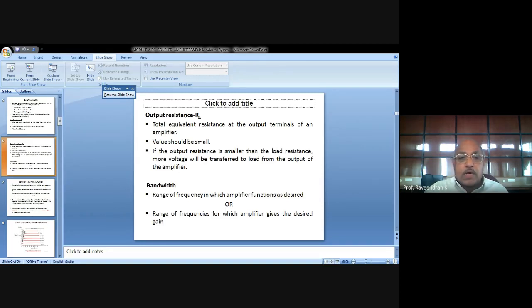You are connecting your signal generator output, that is the input to this amplifier stage, between the base and the emitter through this capacitor, so that only the AC signal will pass through the capacitor and block the DC supply or DC current. So that it maintains the DC operating condition.